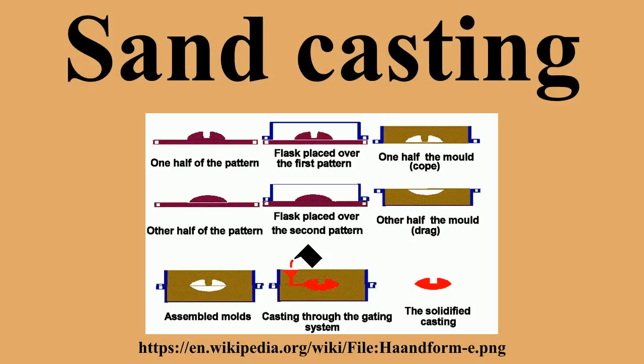The sprue and risers must be arranged to allow a proper flow of metal and gases within the mold in order to avoid an incomplete casting. Should a piece of core or mold become dislodged, it may be embedded in the final casting, forming a sand pit, which may render the casting unusable.